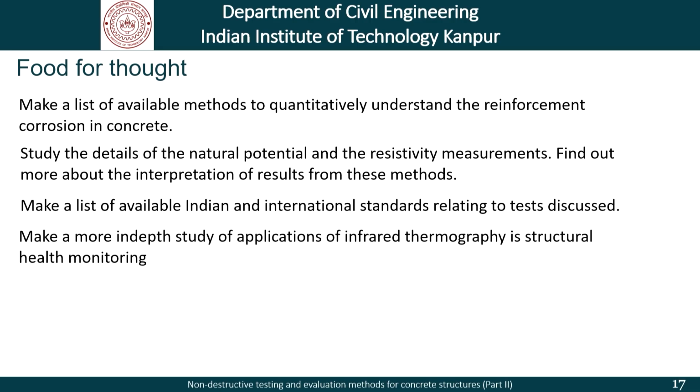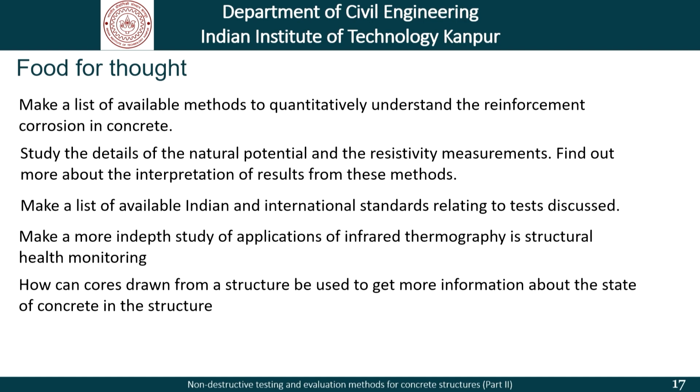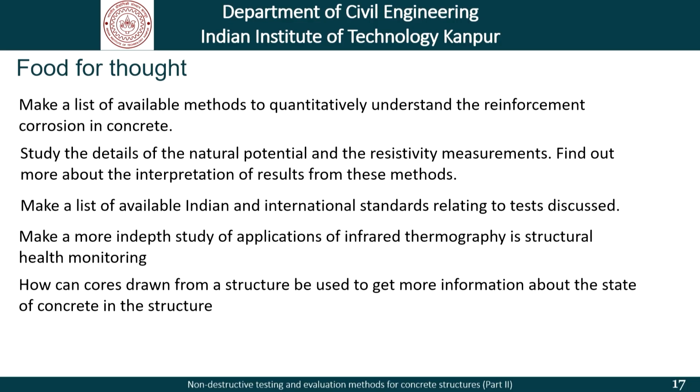Make a more in-depth study of applications of infrared thermography to structural health monitoring, and understand how the cores of the structure can be used to get more information about the state of concrete in the structure. This is something which I had also mentioned to you before we went to the lab, and said that cores can be an invaluable source of information, but the number of cores that can be taken is very limited, and therefore we should try to extract as much information as possible from core samples.